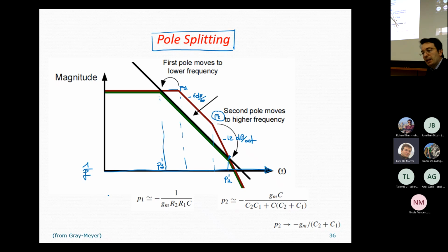For example, in the two-stage CMOS op-amp compensation, we have indeed the effect of the first pole, so the minus 90 degree loss. Then we have the phase loss due to the zero and the second pole.